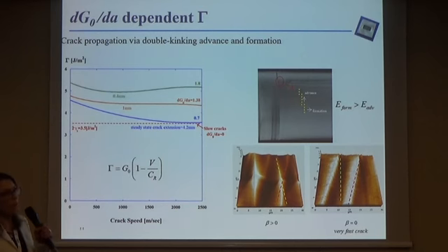So at high speeds, we postulate that the crack front is straight. We have some evidence from Wallner lines where we can see that for fast cracks, the crack front, which is the yellow line, is straight. That indicates that the crack front is straight for fast cracks, while for slower cracks, the crack front is not straight and has an inclination angle that is called beta, which is higher than alpha 0.